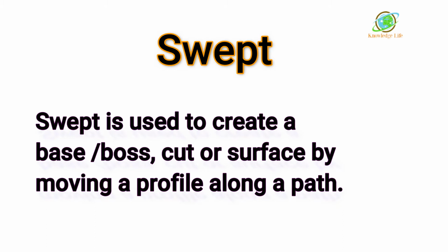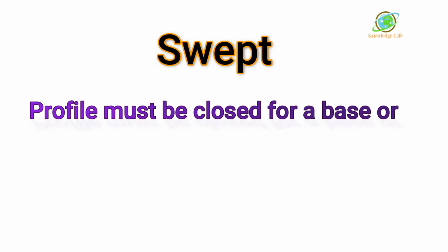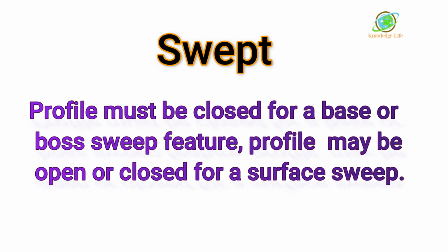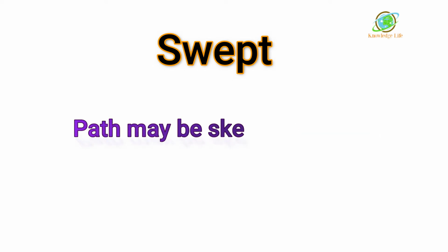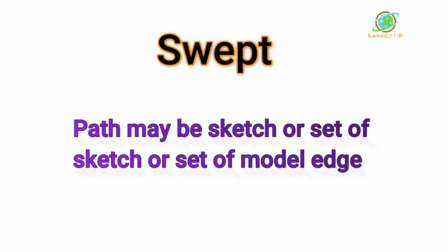Now I will tell you some tricks that you need to remember before doing the sweep. The profile must be closed for a boss base kind of sweep, whereas it can be open or closed for the surface. And the path which you are going to use in the sweep operation might be open or closed. The path you are using might be a sketch, or an edge of an existing model, anything.